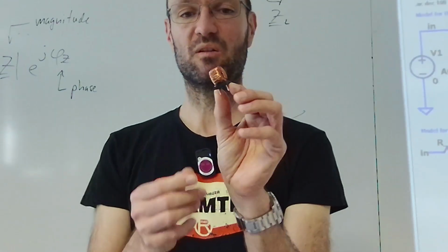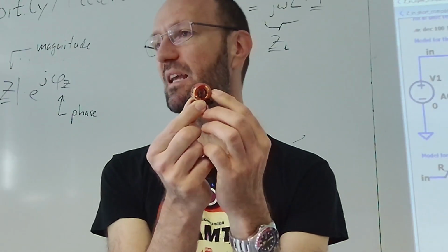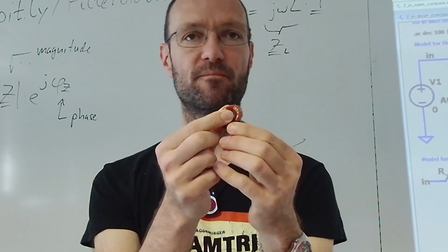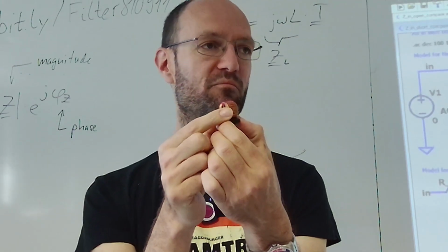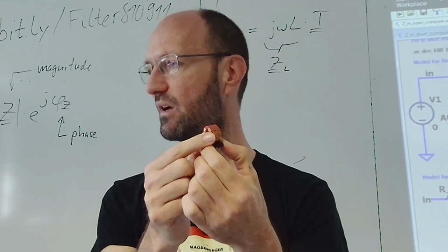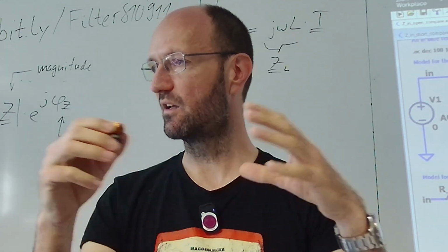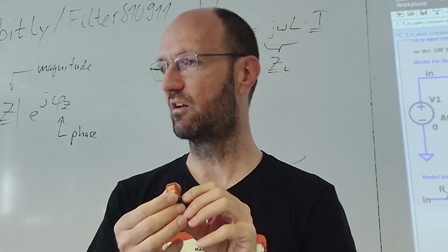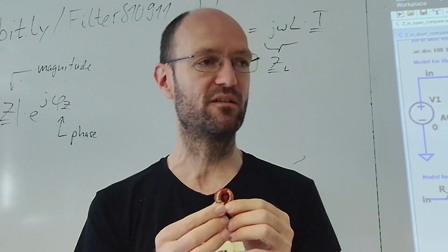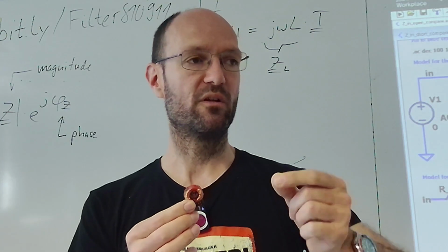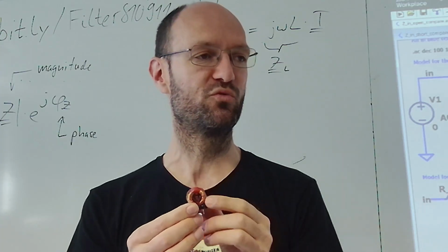Why is this? Because once again, it happens a bit more than just R, L and C in there, because in the copper wire there will be something like skin effect. Have you heard about skin effect? There are also eddy currents in the wire, and at higher frequencies the current will be pushed to the outside, will only flow on the skin of the wire. And this increases the resistance proportionate to the square root of frequency.